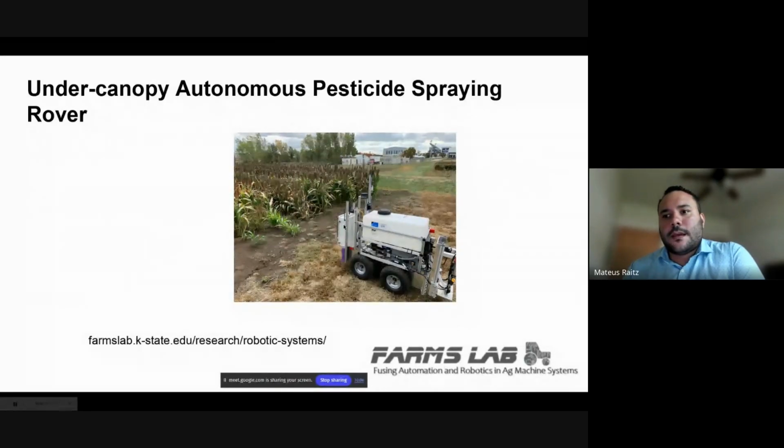But I wanted to distribute the system a little bit. Like I didn't want to bring a bunch of cables for each sensor up to that box. So I thought that we have different options. Like I could have put an embedded Linux computer here and just connected that to the Jetson and have ROS 2 working directly. But that would have been a little bit overkill for this type of situation, right? So we decided to just use a microcontroller, right?